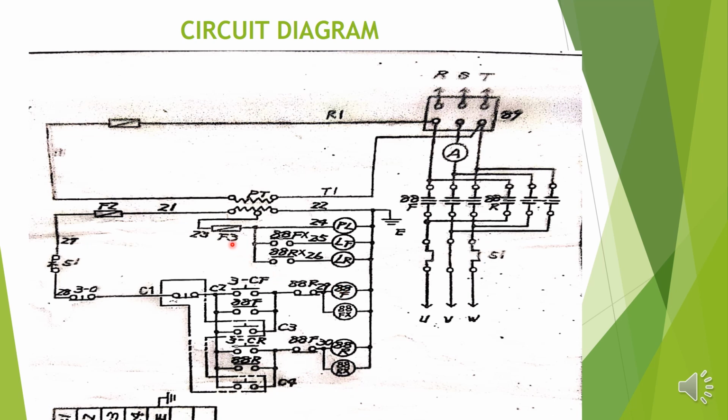So go to the secondary winding of the transformer, and the other side is already connected to the common terminal, everything is common terminal. Okay, so you go to the F2. What is the F2? It is the fuse. And this is the OLR. Everybody knows 51 is written here, you see 51 OLR, that is the OLR control supply. That is, 95 or 96 should always be closed.